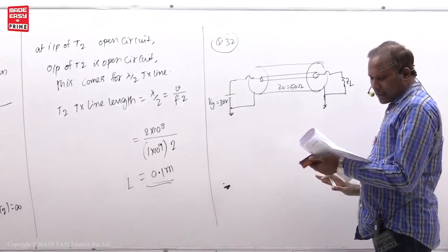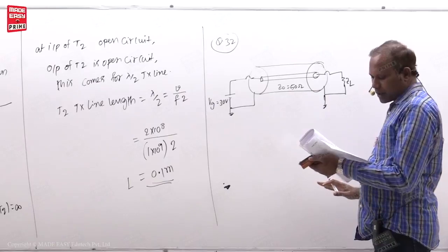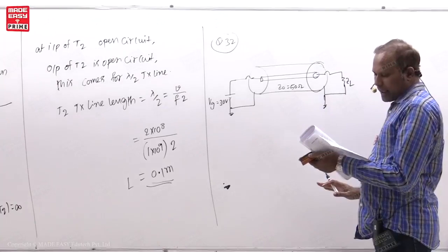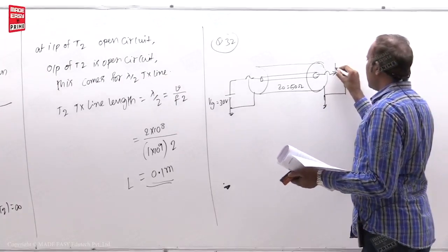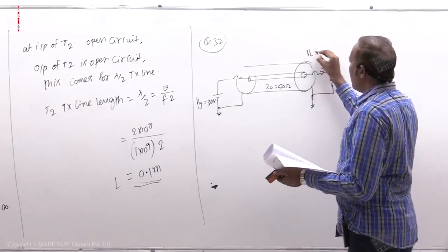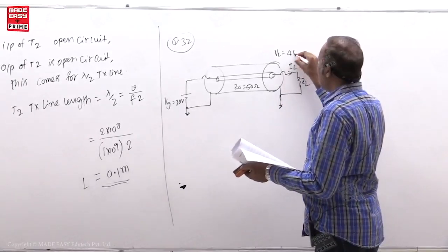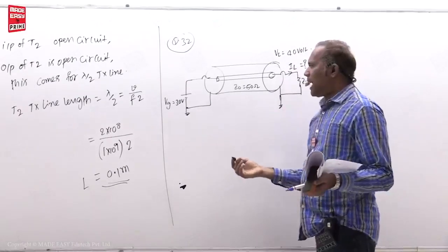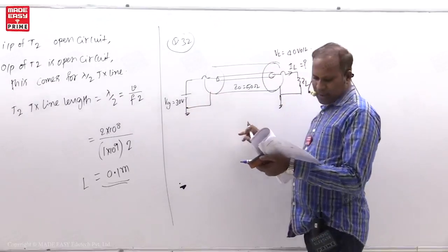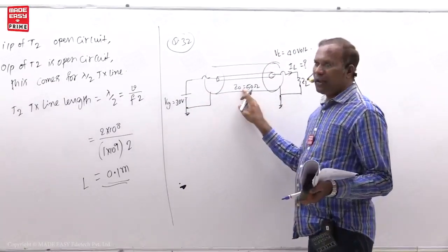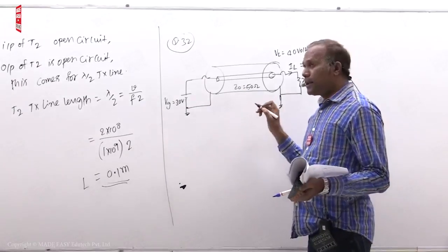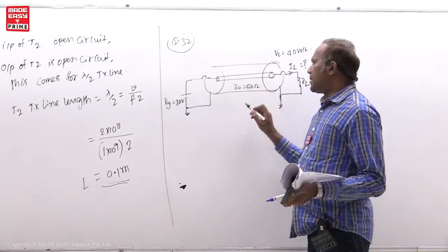The voltage at the load end is found to be 40 volts. Then the steady state current in amperes through the load is... So that means steady state current you have to find. So he has given total voltage at load is equal to 40 volt. So dear student, what is happening here? Source voltage is 30. That means it is a lossless transmission line, because Z0 is equal to 50, that is root L by C, with R0, G0 being zero. It is a lossless transmission line.